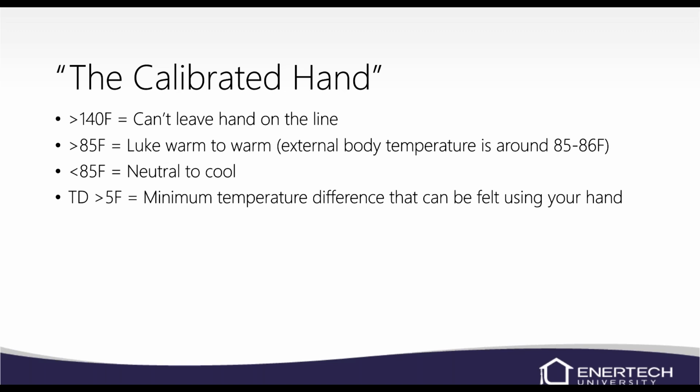So less than 85, it's going to feel maybe lukewarm or warm, or excuse me, anything 85 and above, and 85 and below will feel kind of neutral to cool. You can also, the minimum amount of temperature difference you can feel with your hands is about 5 degrees. So if you ever touch a desuperheater line and it feels the same temperature, there's normally only on a desuperheater about 3 to 5 degree temperature difference. So you may not be able to feel it.